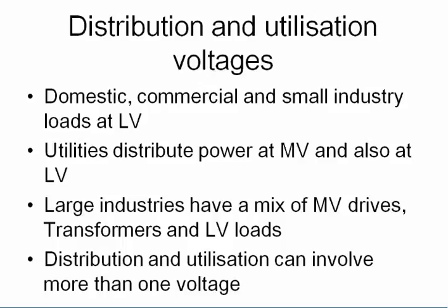Alright, typically you use different terminology. A transmission substation typically refers to where you transform to transmission voltages. So from generation voltage, medium voltage, you transform to 132 kV or 275 kV. That's transmission. While a zone substation, I think you are referring to a zone substation, steps down from transmission voltage to sub-transmission.